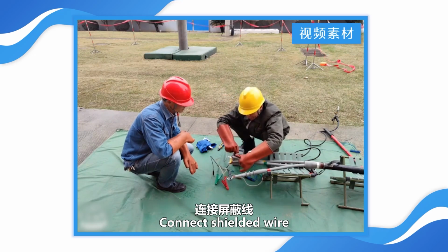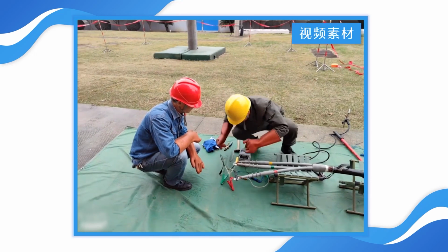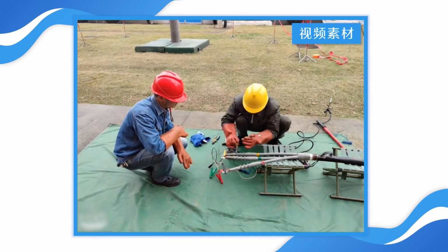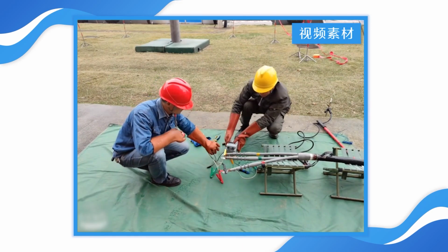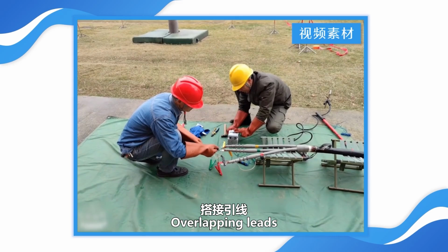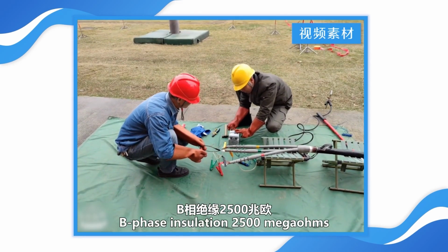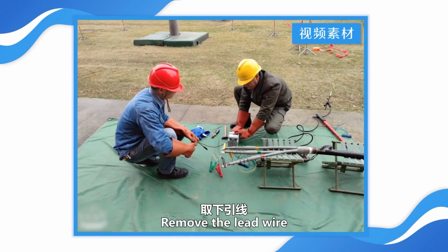Connect the shielded wire. Measure phase B. Connect the L lead. B-phase insulation 2500 megohms. Remove the L lead.